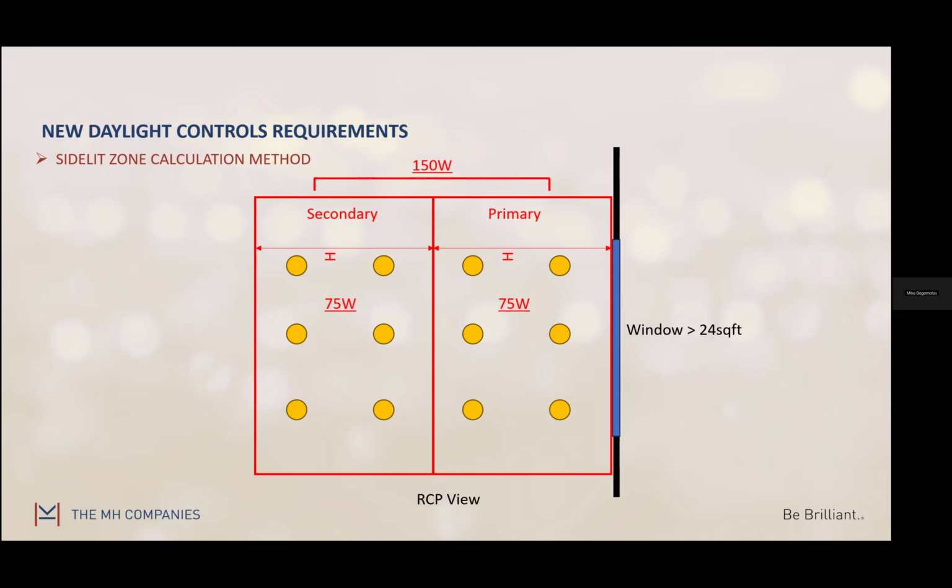The drawback there is that things can move around in the space, especially in an office. Whatever calculations you did when you initially programmed the system, once you move things around, things can change, and that photocell will not automatically recalibrate itself. Whereas closed loop photocells monitor directly underneath the photocell itself and see what's going on in the space.